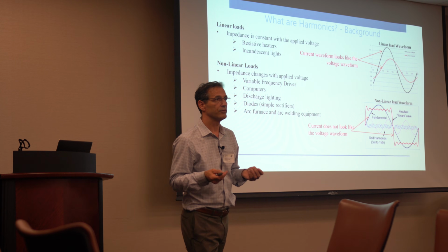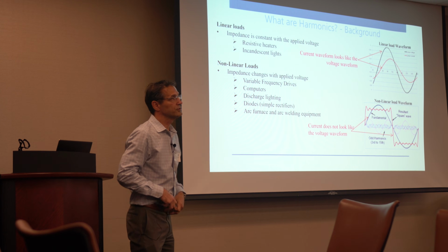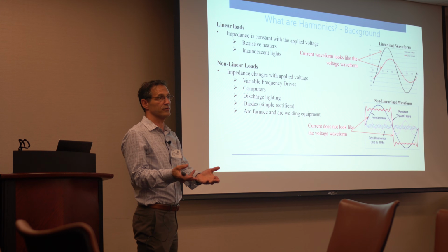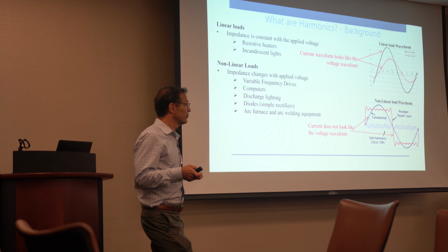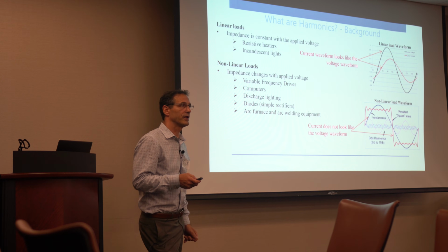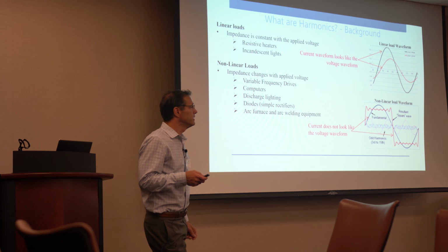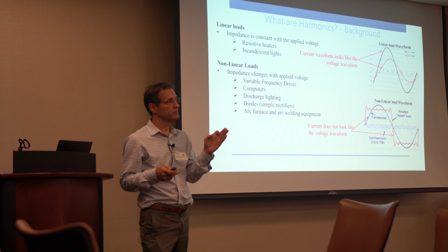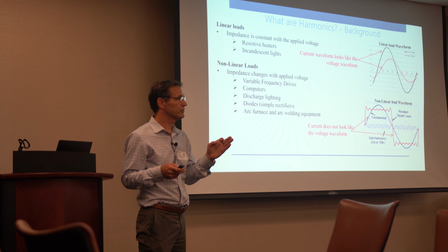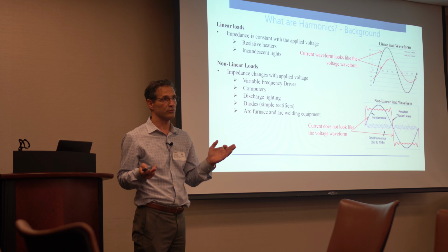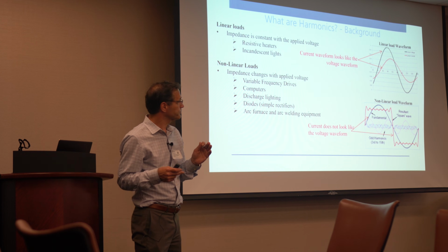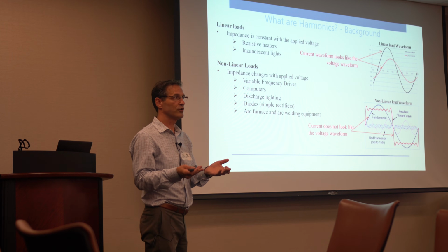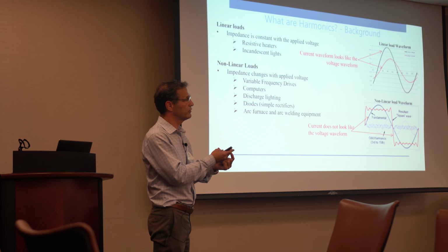And that's your concern. So when you do a harmonic analysis, the first question to the supplier of the drive is, what is the harmonic current output of the device? That's really your concern from an analysis standpoint. The output current from these devices, most of them are modeled in the programs as ideal current sources. It's an ideal current source, which means that if it's, say, a 5th harmonic and it's got a 20 amp current injection, it means it's going to put out 20 amps.